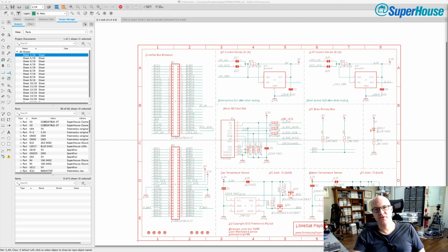So that's the traditional way of doing radio reception. With SDR, software-defined radio, what you do is ignore all of that filtering in hardware. You take the radio signal that comes in, amplify it, and then you have a raw signal, which is basically like a garble of everything all overlaid on top of each other, and you feed that into a computer so that the signal ends up in the software realm. And then instead of doing things like the frequency filtering in hardware, you do it in software.